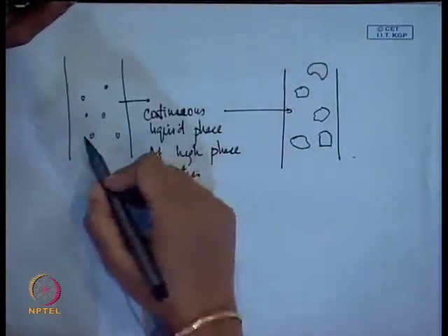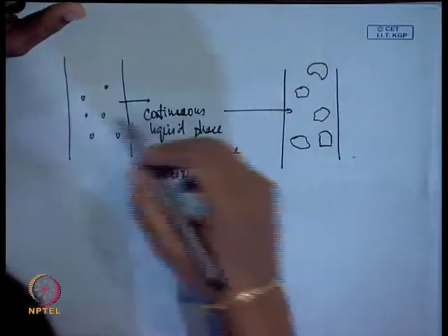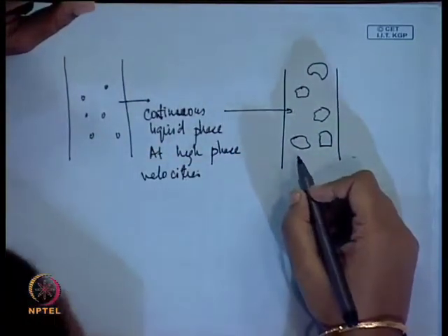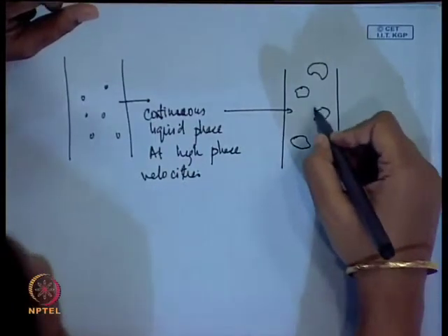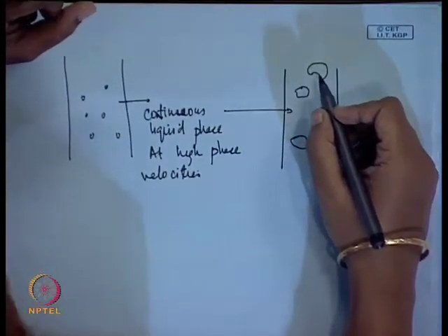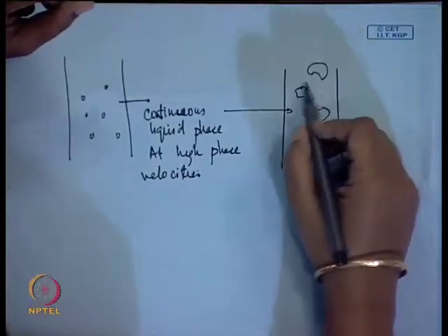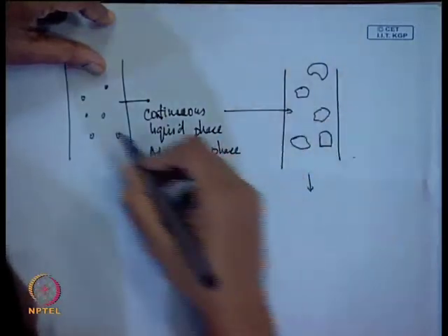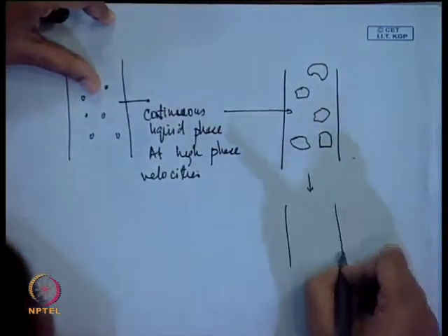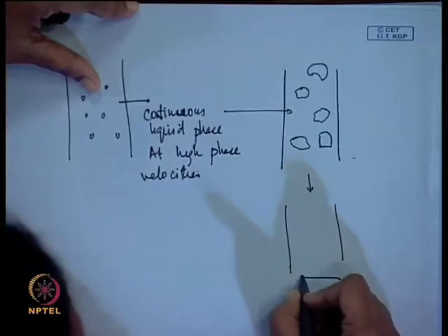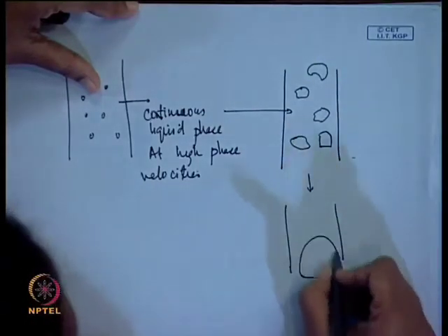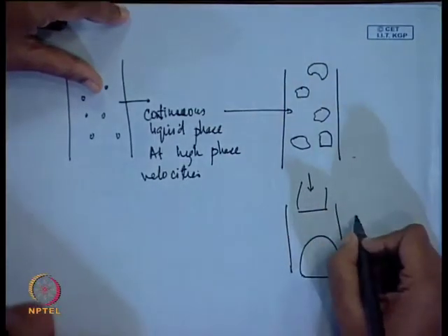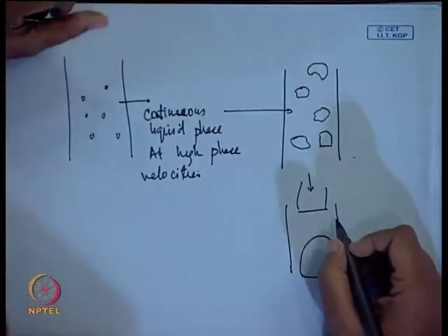Now, we find that in both the distributions it is characterized by a continuous liquid phase where the dispersed phase is the gas phase, but the dispersed phase can take on a variety of shapes and sizes. In the limit, as we keep on increasing the gas velocity, finally these bubbles coalesce and form Taylor bubbles and liquid slugs, where we get the slug flow pattern.